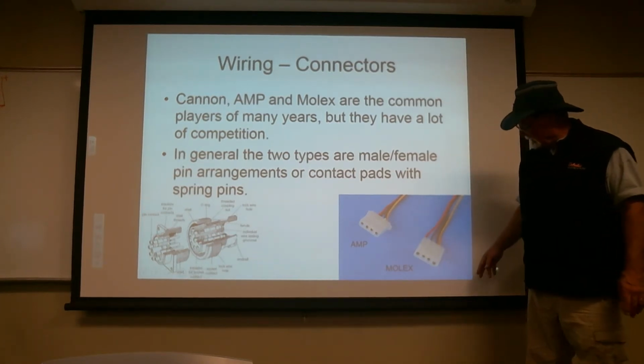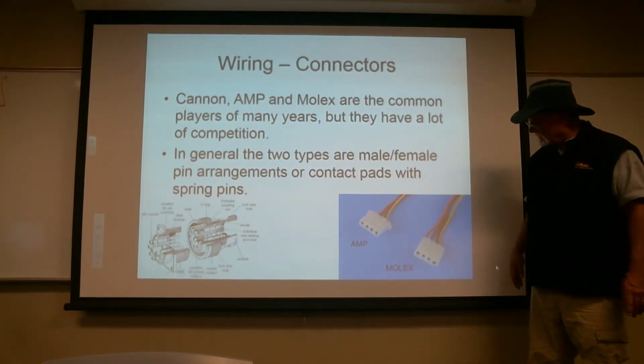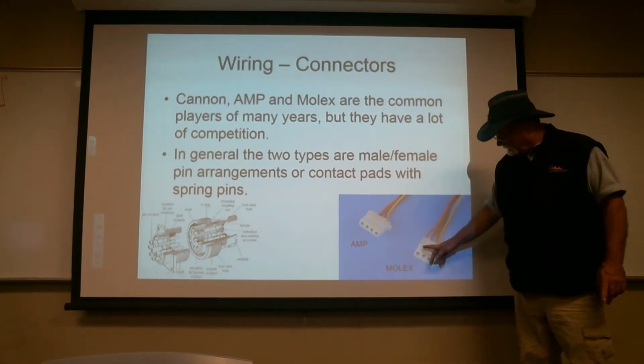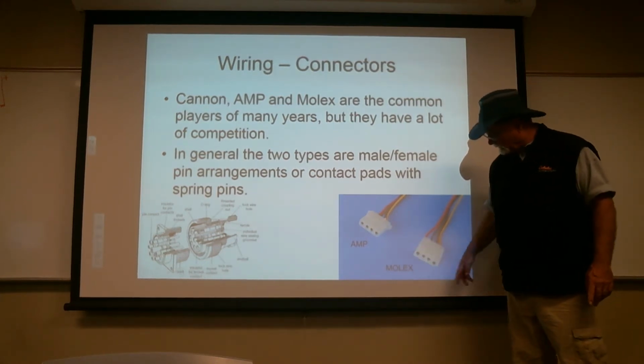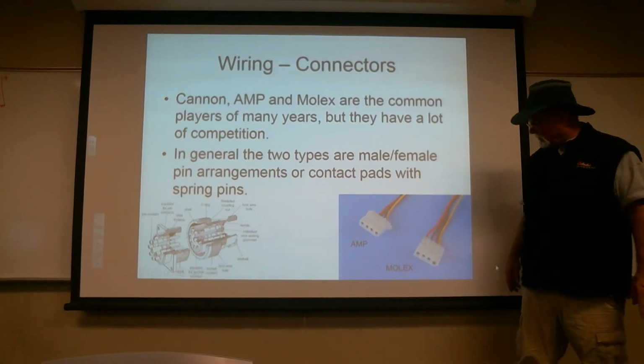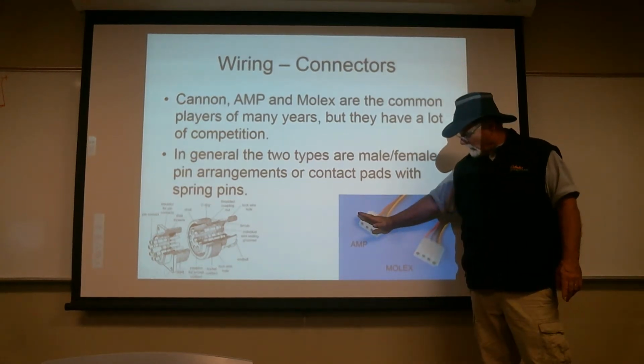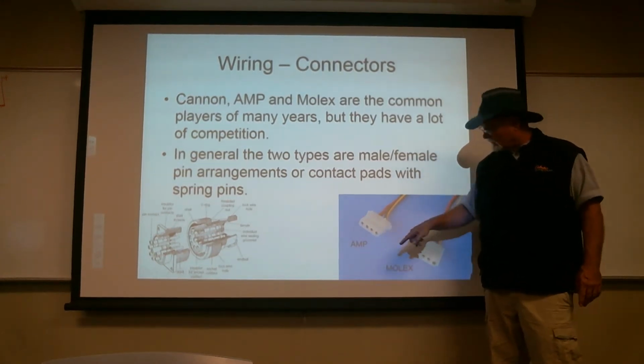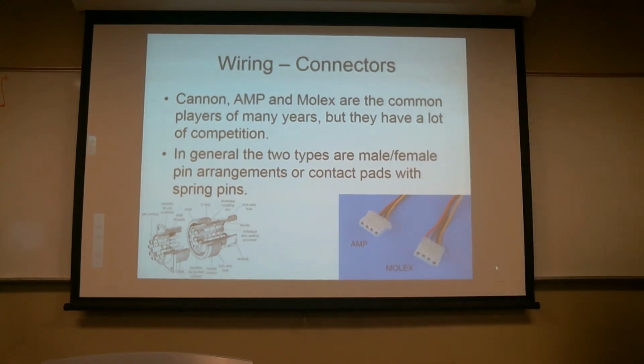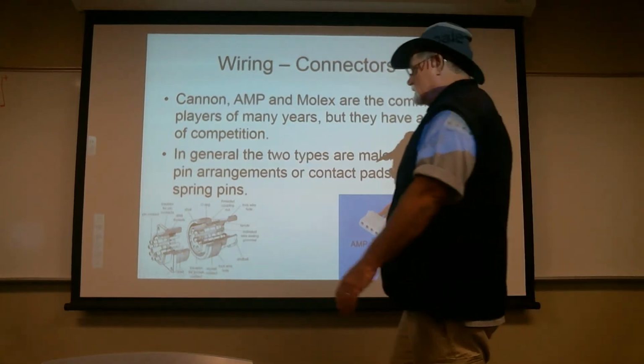So note, here's a couple of examples in the world of computers. Molex, in most of theirs, they tend to do a square corner and a sharp corner like a little boat. Here the square is on this side and the chamfered corners are on that side so that the connector is indexed. It can only go in one way. Most connector strategies call for it to be indexed so it can only go in one way. That's not universal, but most of the time they do.